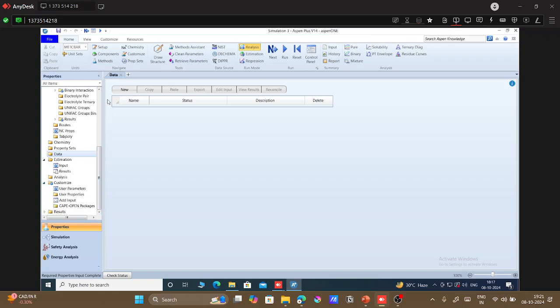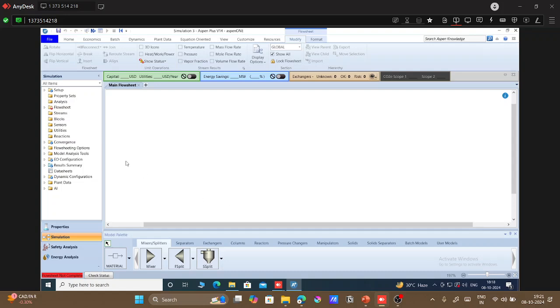Oh sorry, this conversion part will come in the simulation part, not here, my mistake. So let's run the simulation. Property analysis is done. Now let's go into the simulation part. Here we should be able to select the conversion part. So in the conversion we have conversion options.